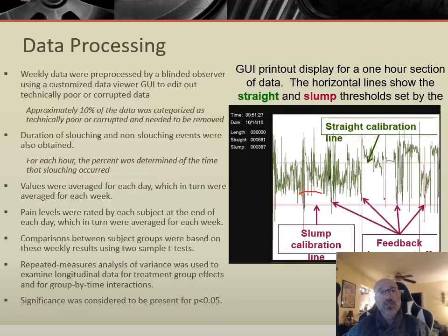What are these disturbances? In particular for this project, we were getting some very strange signals that were all over the place that weren't just our data that we were interested in. It was coming from the fact that we did not have a common ground within our electronics, and the sensor was actually picking up frequencies from some of the fluorescent lights in the room.